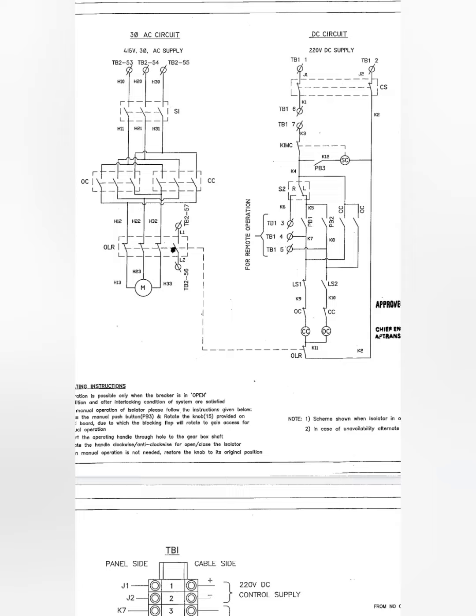The AC supply is for the motor, a three-phase motor has been used. So for that we are going to give a three-phase supply, and this motor is delta connected, that's why we have not mentioned the neutral supply. And also another thing is that in between the motor supply we are going to connect OC and CC contacts. So if we need to open or close, from that the coil energization will be carried out and the coil contacts will make as per the opening and closing.